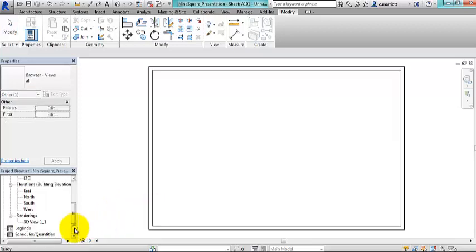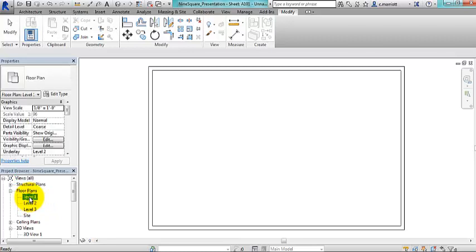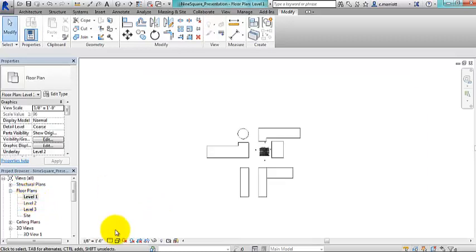All right, so what you'll see is in the list of sheets, I now have one that's called A101 unnamed. And what I'm going to be doing is dragging the drawings to this sheet and arranging them. So one thing that you'll want to do is go through and make sure your scales are correctly identified, whether it's 1/8 inch, 1/4 inch, etc. And you can go through that.